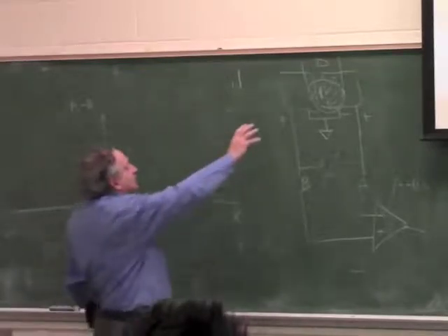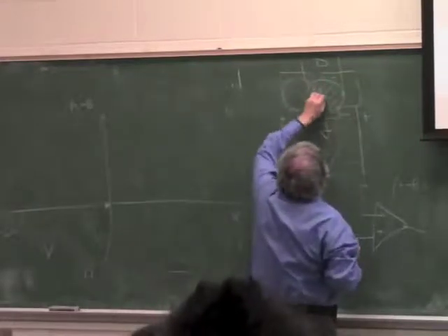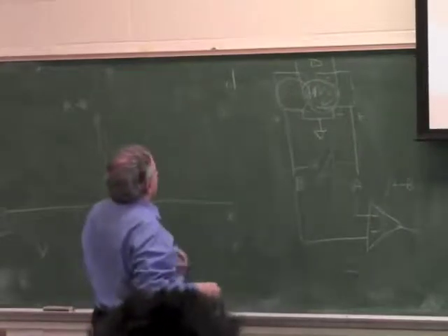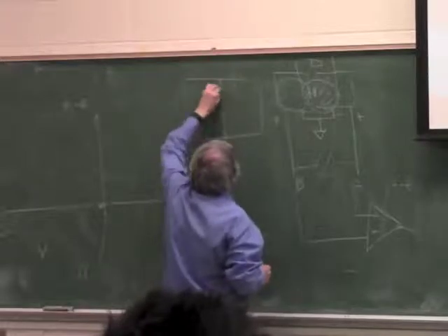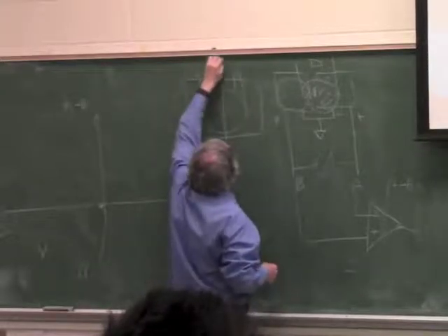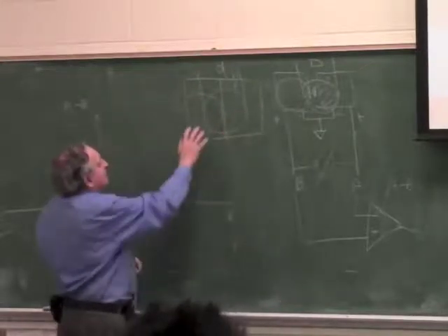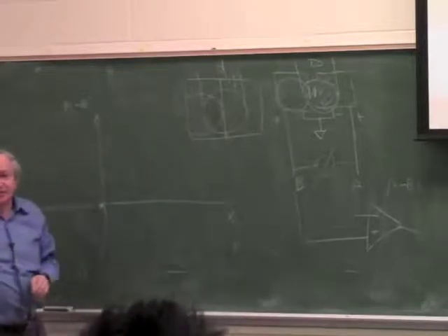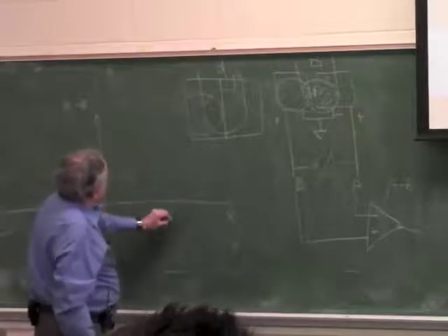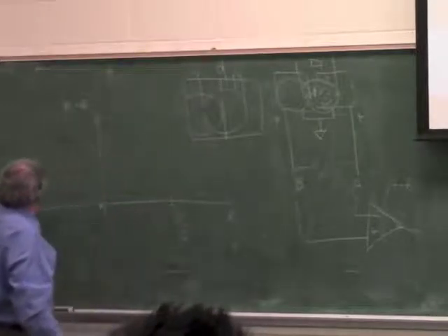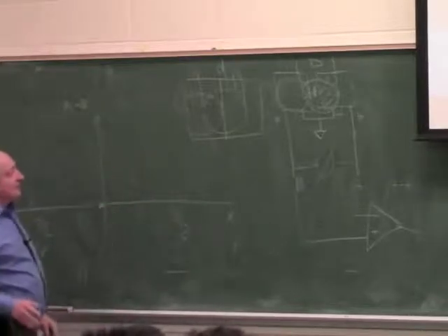Now, as I start moving this, it will keep changing until I moved it by a whole unit of D over 2. Because it's a 0 position, to simplify it, this was a 0 position, and when the circle reaches here, this photocell has no light, and moving the circle farther doesn't make any difference. So I will have a linear range from 0 until plus D over 2 and minus D over 2. And over that range, it wouldn't be exactly linear.